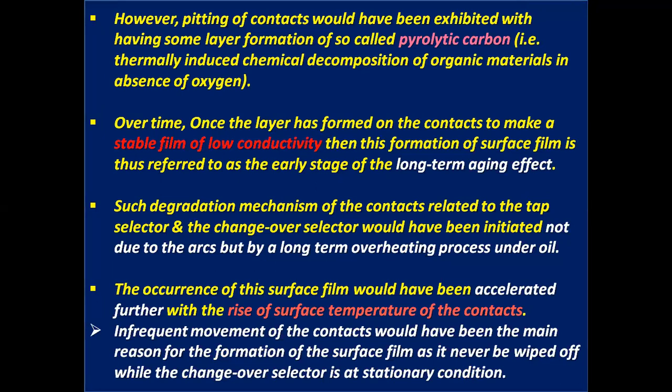However, pitting of contacts would have been exhibited with some layer formation of so-called pyrolytic carbon, that is thermally induced chemical decomposition of organic materials in absence of oxygen. Over time, once the layer has formed on the contacts to make a stable film of low conductivity, then this formation of surface film is referred to as the early stage of the long-term aging effect.